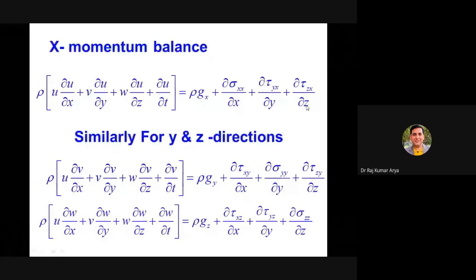Okay. So why are we converting all these things into velocity? They're doing that because to measure the stress on a fluid or on a particular element, the easiest thing for us is just to measure a velocity. Velocity we can measure. We have a flow meter, we have a pitot tube, which gives the velocity at any point.